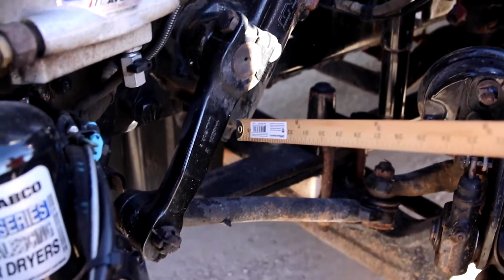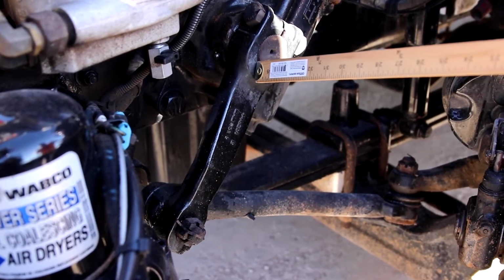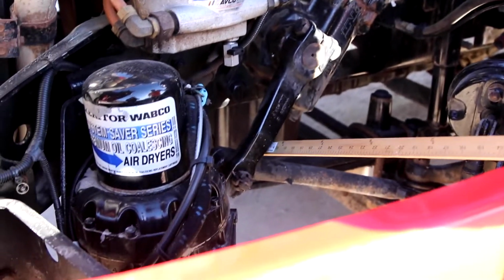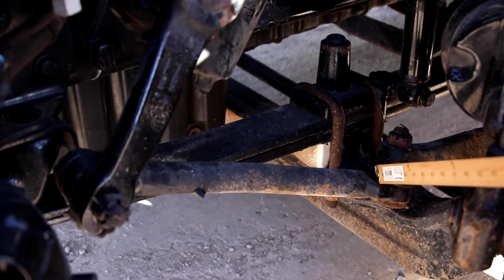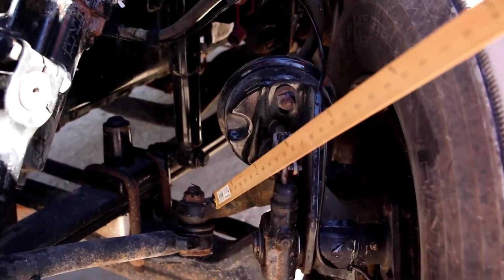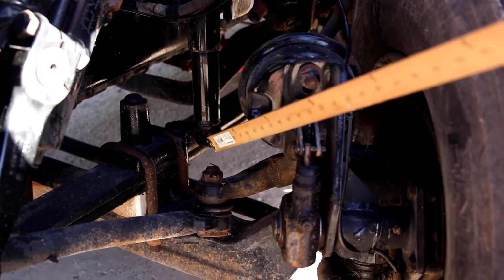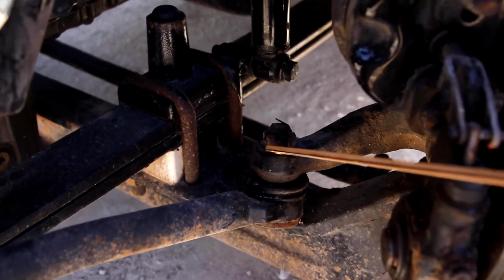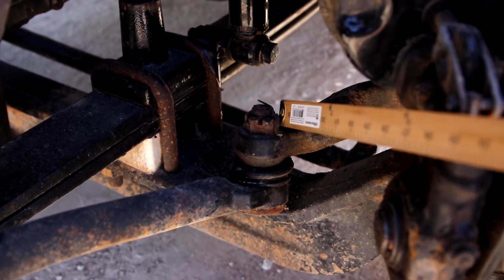Then you have your pitman arm, this long piece right here. This is your pitman arm. It is mounted securely to the gearbox. It's not missing, damaged, or broken. This piece here is called your drag link. It is not missing, damaged, or broken. This piece right here is called a steering knuckle. It is mounted securely to the vehicle. It's not missing, damaged, or broken. And these pieces are held in place with what they call a castle nut and a cotter pin. It's a wire pin that goes through and locks the nuts into place.